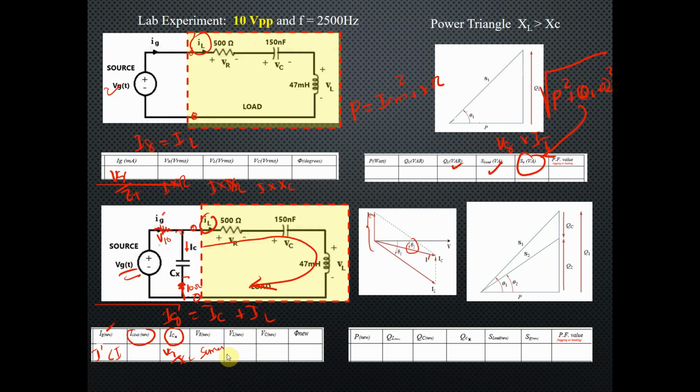Also BL is the same, and also BC is the same. It did not change. What will now happen to the theta new? Theta new will be very close to zero, right? Power factor will be unity. So again, what can you say about the power here? The power here after providing the capacitor will be the same as the power on the original circuit.